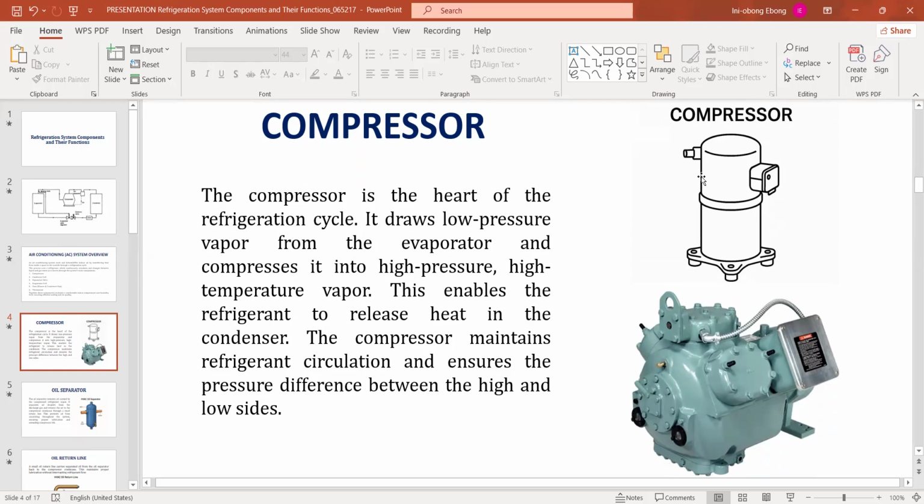And of course, if it is single phase and that compressor does not start, it does not really mean that the issue is the compressor. In every single phase induction motor, we require a starting capacitor to start the motor. As we progress, we'll digress on that.